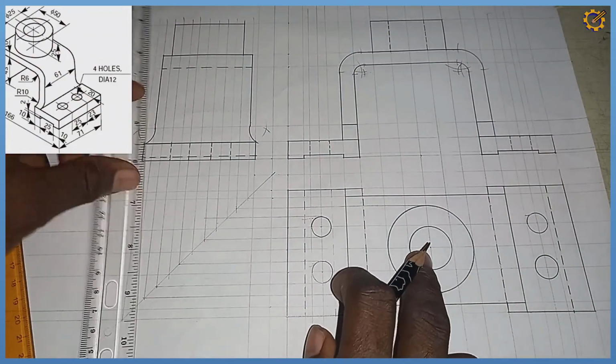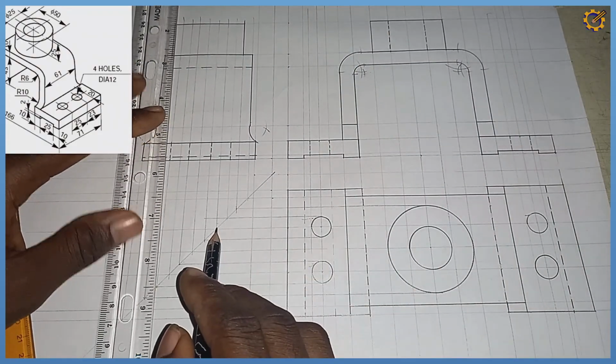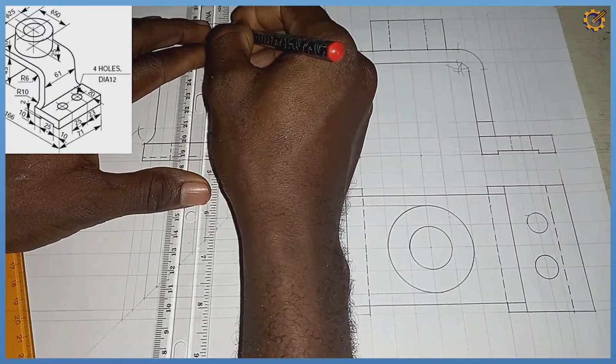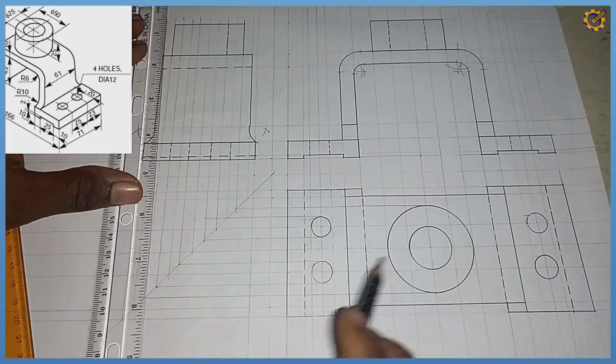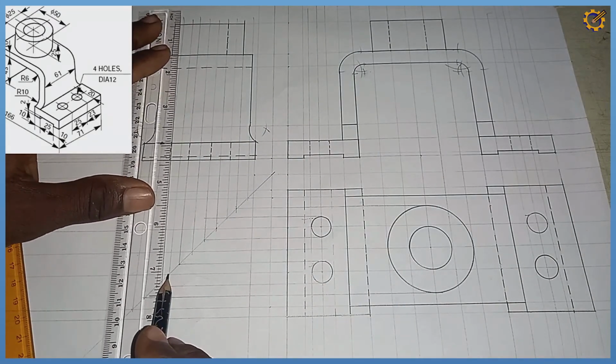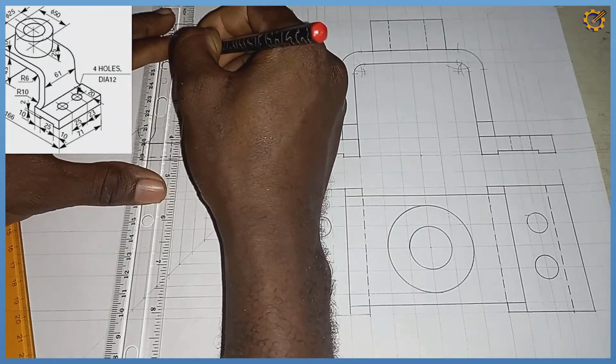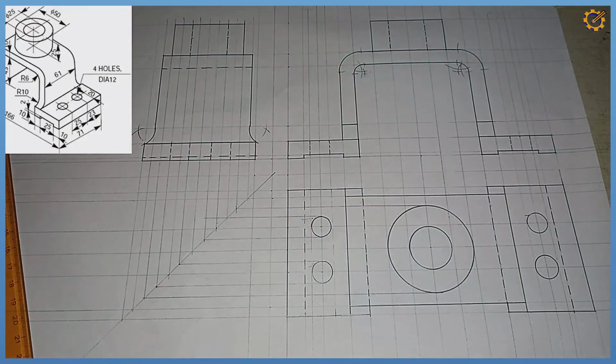So then the inner cylinder will be hidden. Tracing it, this is the first leg. Then to the top it will be hidden like this. The second leg, tracing it, this is it. So to the top it's hidden like this. So that is that. That is the complete representation of the object on the screen in first angle orthographic projection.